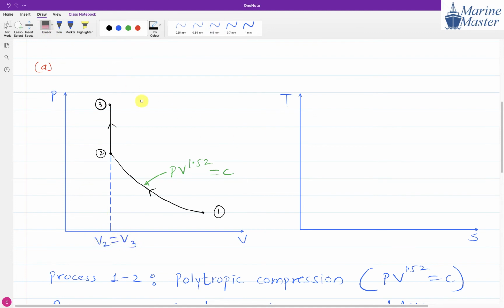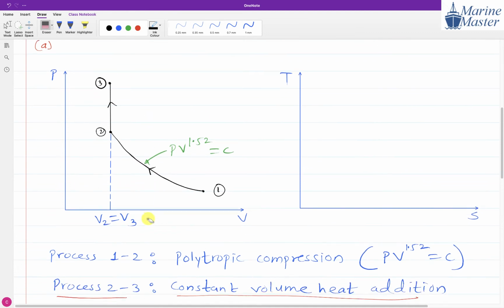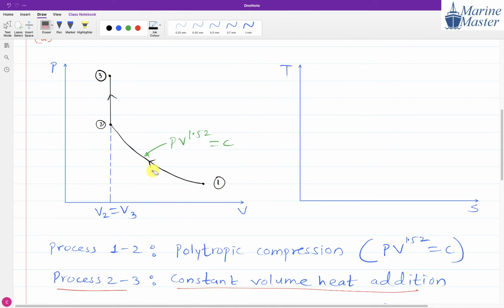Now, before going further, we will not draw the TS diagram at the beginning, because here we have a polytropic process. For a polytropic process we will not draw the TS diagram in the beginning. We will draw the polytropic process TS diagram at the end of the numerical, because for a polytropic process we should know some things. Before going further, just complete this PV diagram, where we have drawn the axes of PV and TS. Complete this PV part, pressure volume.